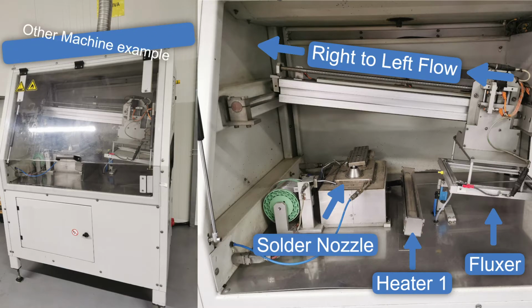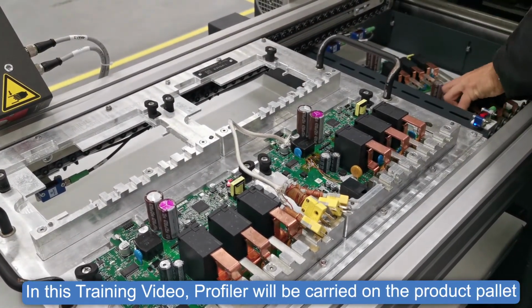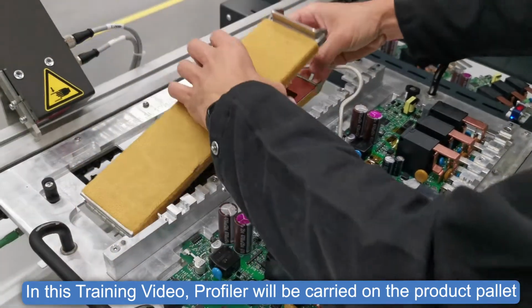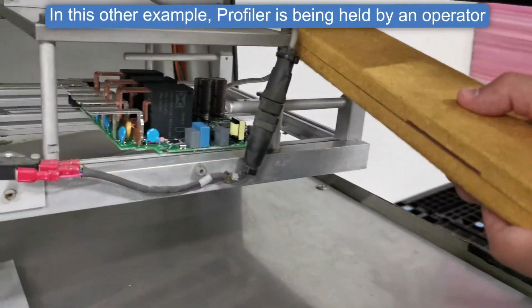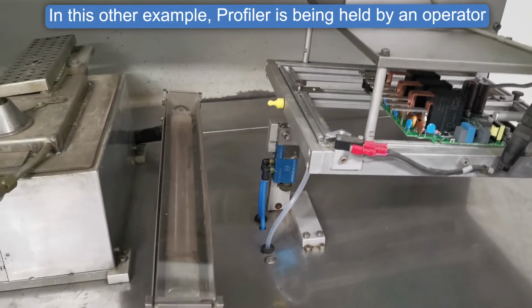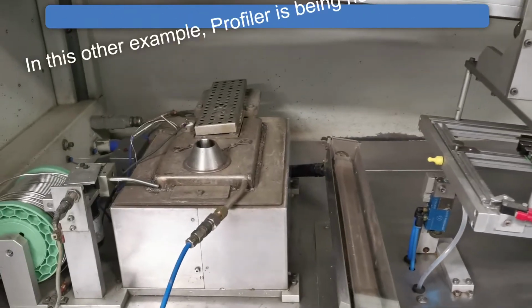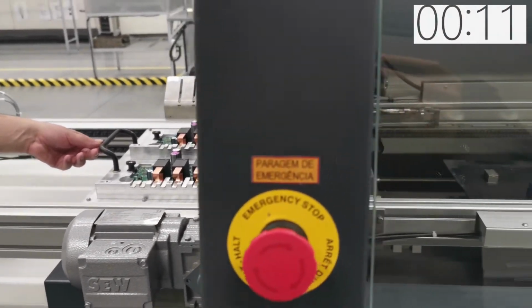Some selective solder hardware designs will not lend themselves to pass or carry the profiler behind or close to the profile board. In some cases, the profiler may have to be held by an operator during profiling, and in others, the selective solder machine may not lend itself to be profiled at all due to physical constraints or safety reasons. Let's start the evaluation where the process starts and stops.